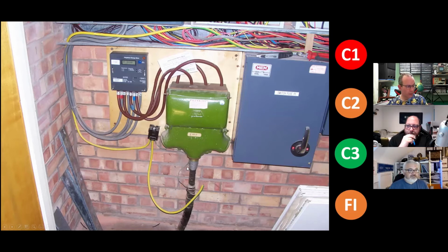Effectively what it is. I have actually seen people lug these and bolt them onto the casing screws. I've seen that before. I've seen Sparks actually cut off these little, what they consider straggly bits of wire, and then bolt it to the metal casing of the cutout. I've seen that done on a lot of occasions. Not good. Ring the DNO. That's Sparks interfering and manipulating stuff that shouldn't be.